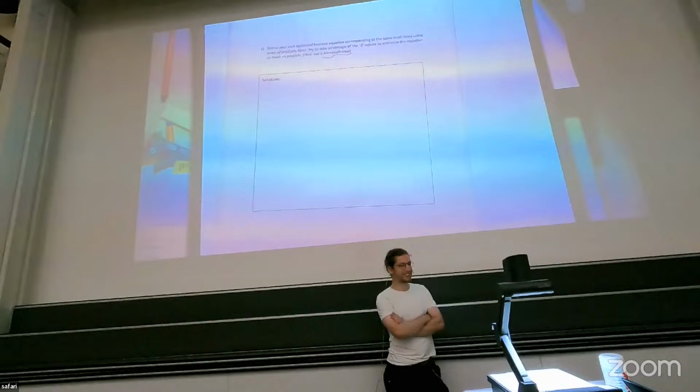Did that make sense? The trick here is the output, I want 64 bits. I realize that I have a 32-bit memory, and I say, okay, I need 2 of them, 2 kilobytes. I need to make it in this way. It's very simple. They use the same address. This guy gives the upper 32 bits. This guy gives the lower 32 bits. So if I'm writing in it, the upper 32 bits goes here, the lower 32 bits goes here, but they have the same address. Okay? So that's solution number 1.